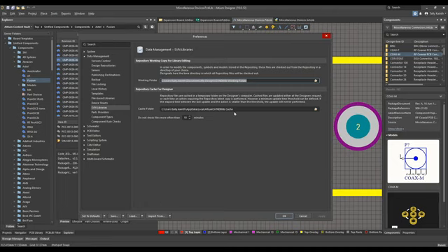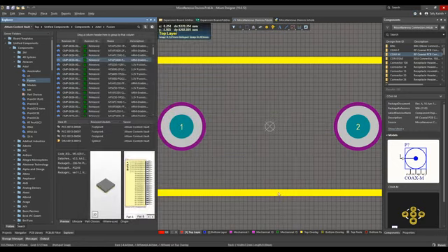There is another means of storing and accessing components at a company level within Altium. This is similar to the Altium Content Vault, but instead of being online and public, it is a company private vault called Concord Pro. In many ways, this provides a number of features: company-centric control of parts, a common part source with version control, and tracking features such as where used. As demonstrated, Altium supports a number of libraries. It is up to you to decide what works best in your environment.